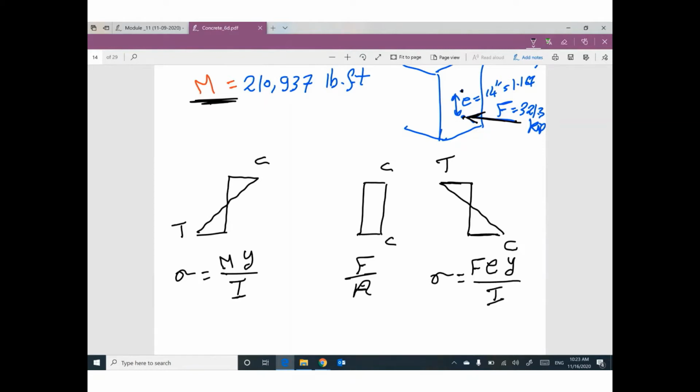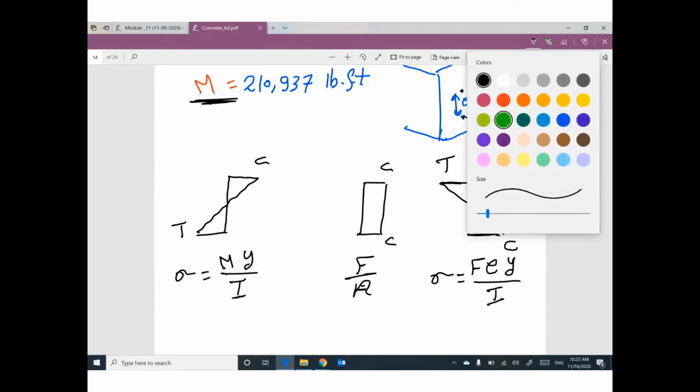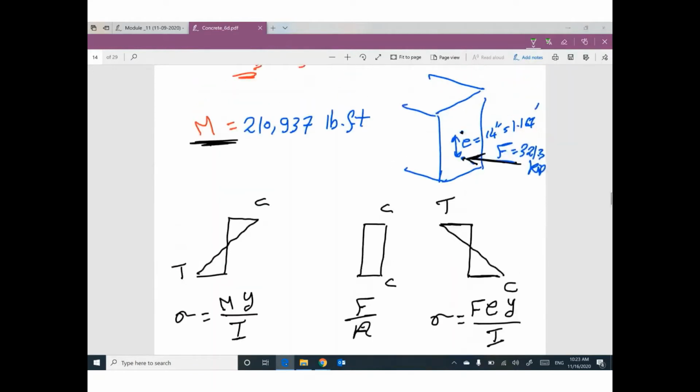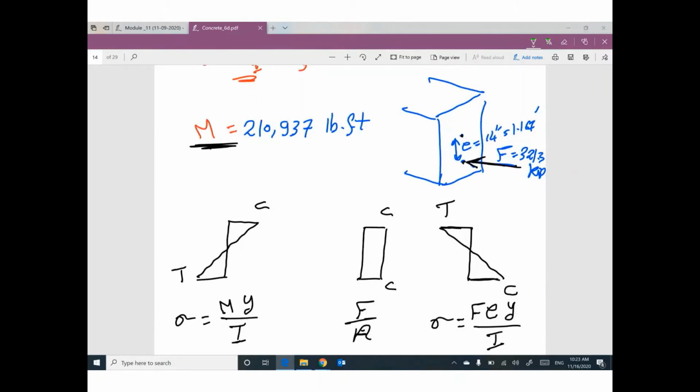If you go back to our last meeting, you can find the three cases. I know some of you will ask this question. It's a very good question, and please make sure you can get it. The effect of this pre-stressing force is acting at the bottom. So at the bottom, we have compression. That means at the top, we will have tension.